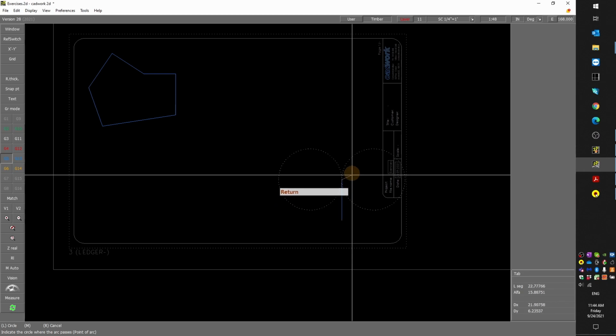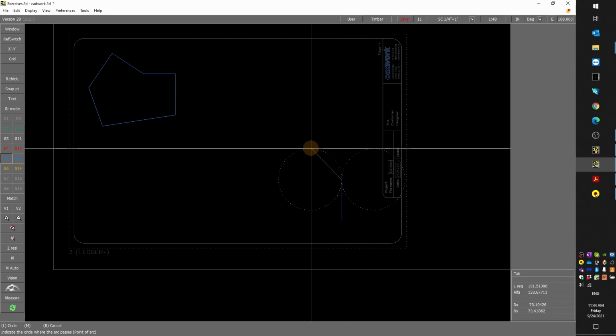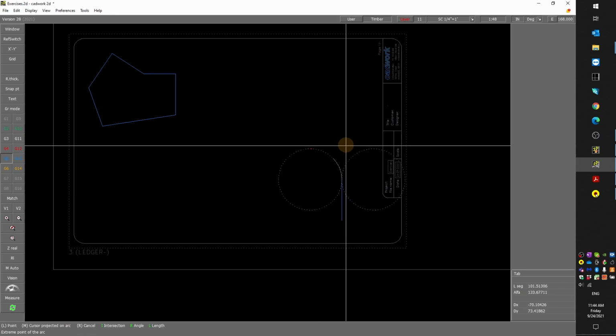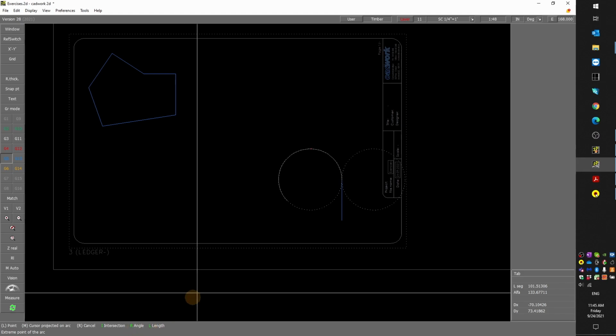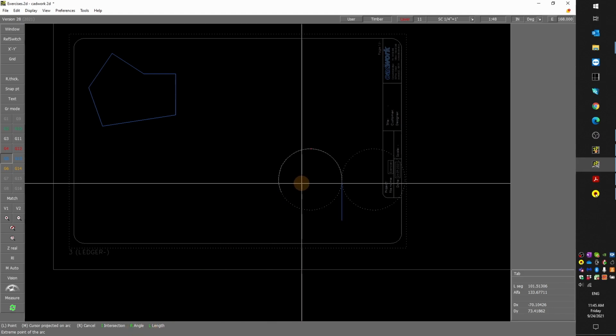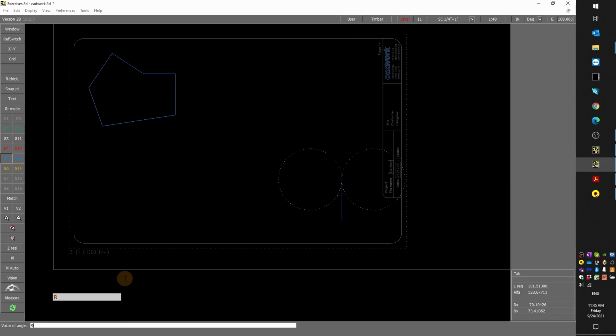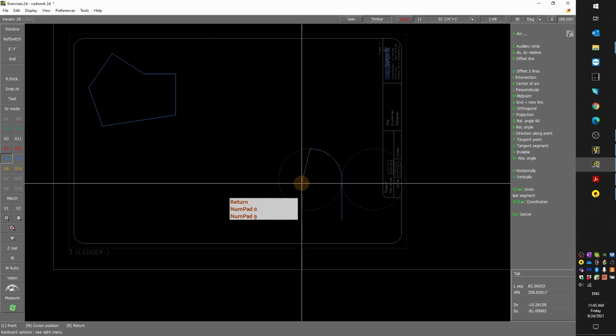And then I have two options. So I'm going to click up here. That's where I'd like to go. And you see some options appearing. I can either set the length of the segment or the angle. So here in this case, I know the angle, 90, enter.